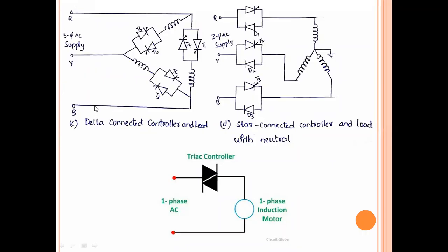That is very much essential for the power electronic converter circuit, which is a major disadvantage. Because all the power electronic converters are non-linear circuits, definitely every non-linear circuit will produce a power factor issue at the AC input terminals. This is a very important point. You remember this one. For any circuit, either three phase or single phase or anything, if we are using a power electronic circuit, then it will create a power factor issue because the distortion factor is very high along with the displacement factor. Those cause the poor power factor at the input terminals.